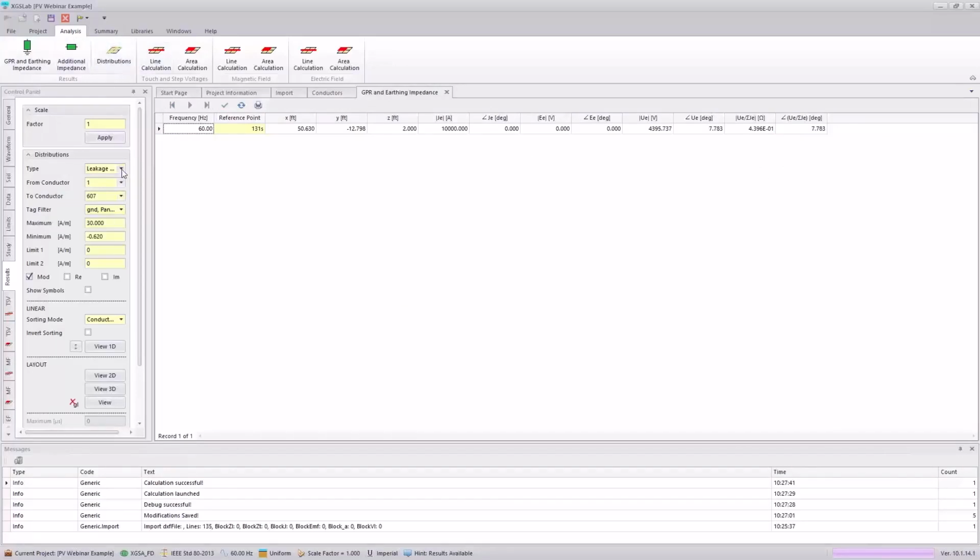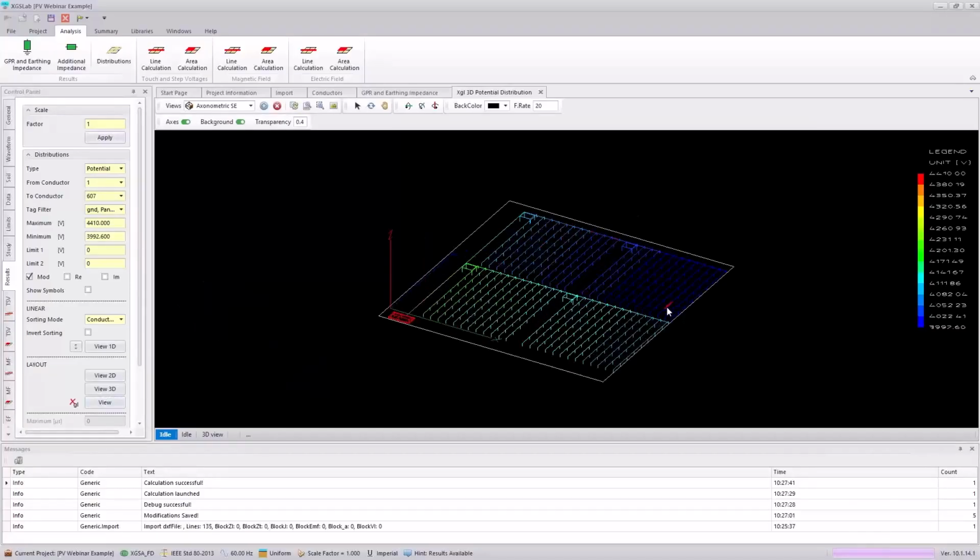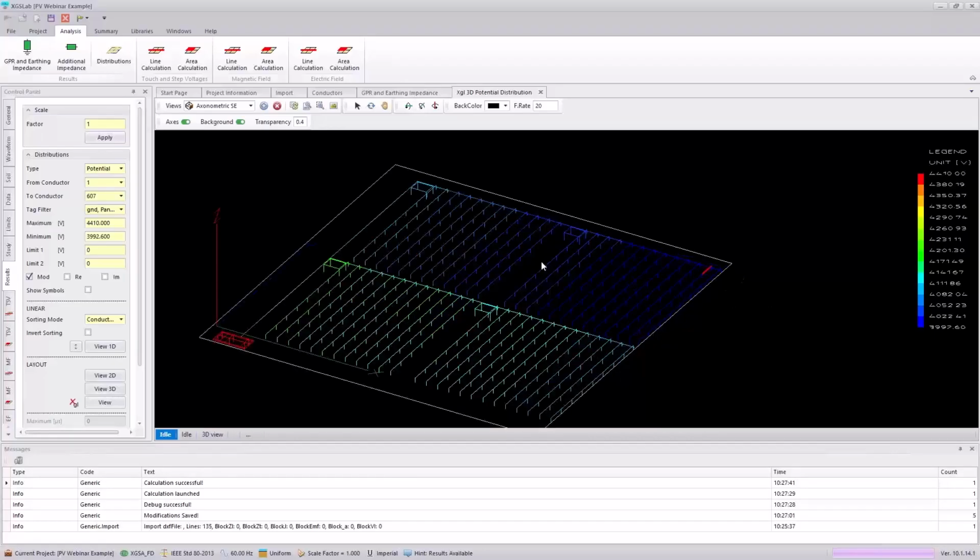With my analysis, what I want to show is its voltage potential. So one challenge I think that many engineers run into when they're doing a grounding system analysis for photovoltaics is that if they're using a simple tool, that tool is likely to use an equipotential plane assumption. And what that means is essentially all of the conductors in my model are assumed to have no voltage drop. They're superconductors, and the system's really calculating the impedance based off of the area of my grounding system, not so much how the voltage is going to propagate through this system.